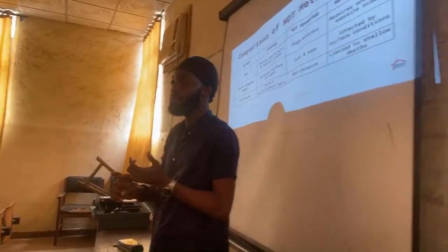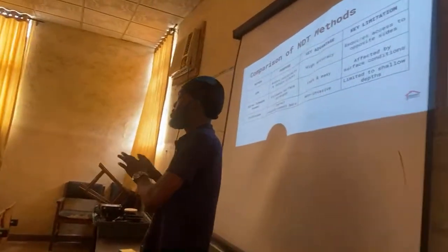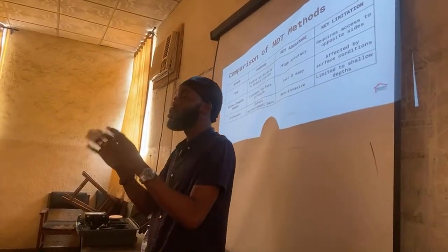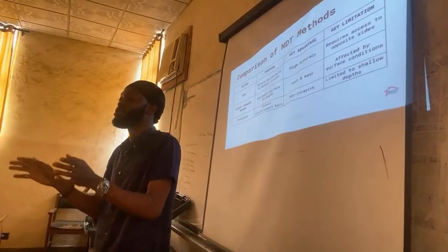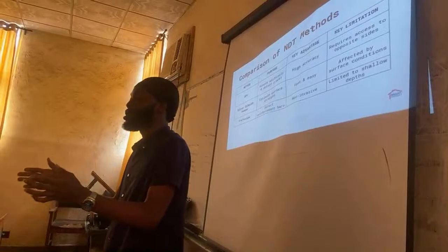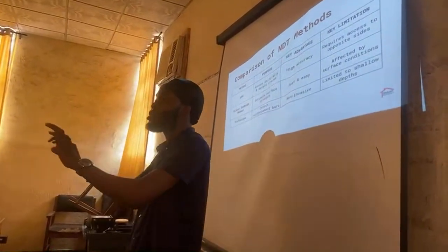For something to have been corroded, there must be infiltration of water and exposure to air. So I'll talk about something relating to the Schmidt hammer, that's carbonation. It's a chemical process whereby CO2 reacts with calcium hydroxide in the cement paste of the concrete, and it will form calcium carbonate. That is like the rusting process.